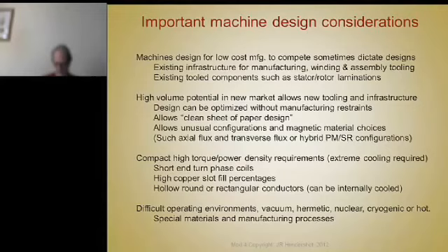And those are fine, and they have some features, but the problem is, historically, those kinds of machines seldom, if ever, get into production because they require so much new infrastructure and new tooling and new thinking about manufacturing. So that's important to think of. That's one of the difficulties with pancake motors or axial flux motors. Sure, they have very high torque density. They have a lot of wonderful features going for them, but nothing about the components or the manufacturing is like any other motor, so they're not standard.